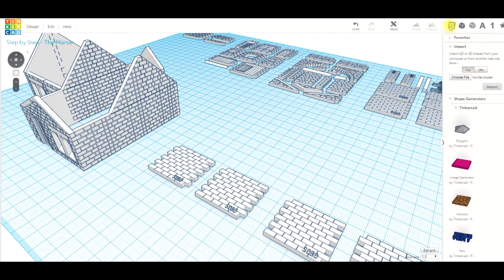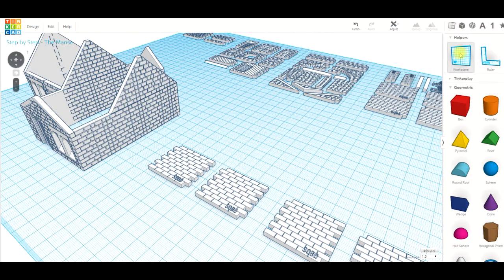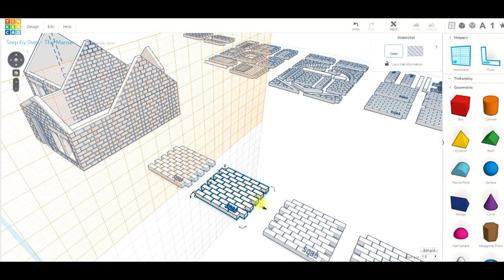Okay, so clicking on the helper shapes grid and the work plane tool, which we've done before, I'm going to slide that to the inside marker of one of the roof sections. Click the first roof section, hold over it, and I can see that I'm 12mm away from connecting it. Slide it in carefully until you get it to 0. Just a little bit delicate on the mouse.